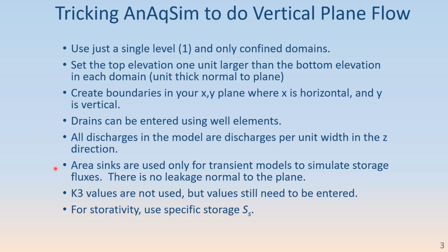Area sinks will only be used in transient models to simulate storage fluxes. There's no other purpose for them, since there is no leakage normal to the plane like you could have in a typical multi-layer model with the domains horizontal.